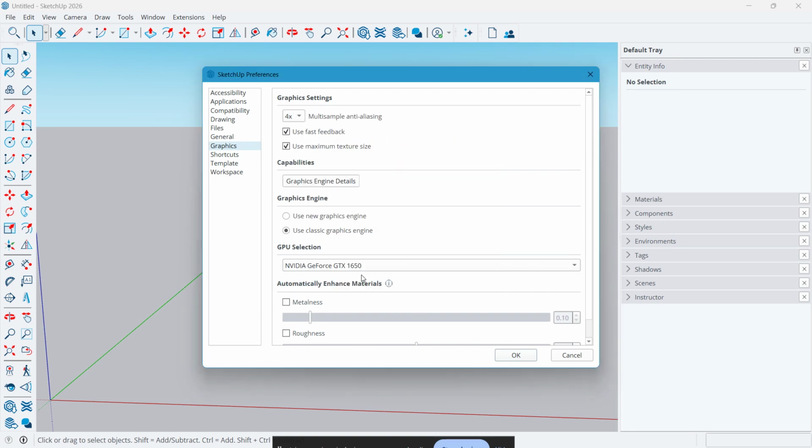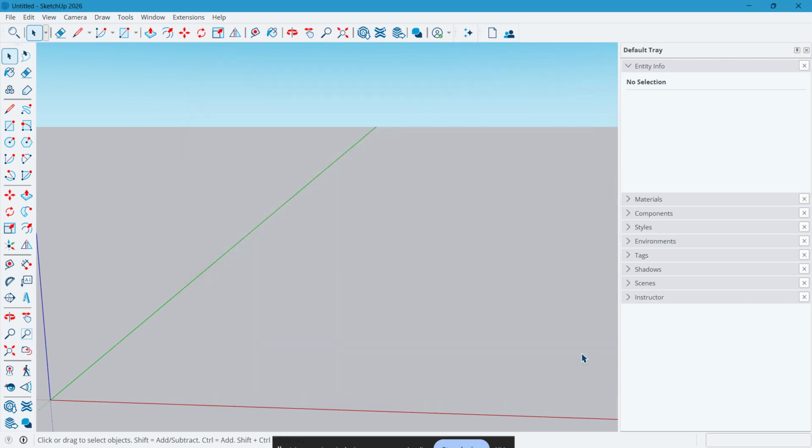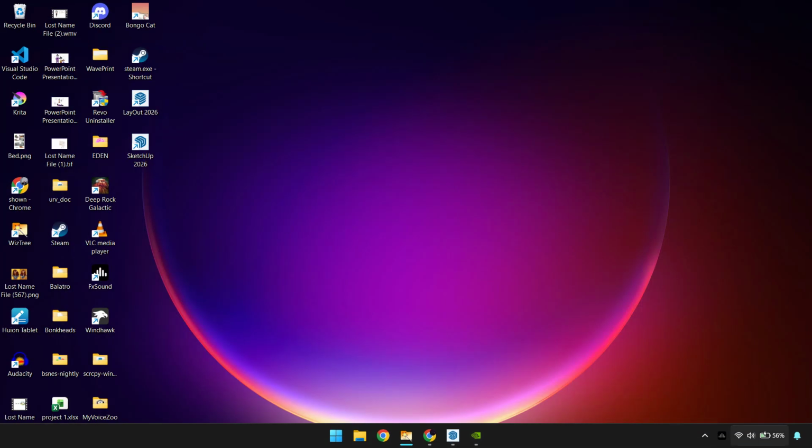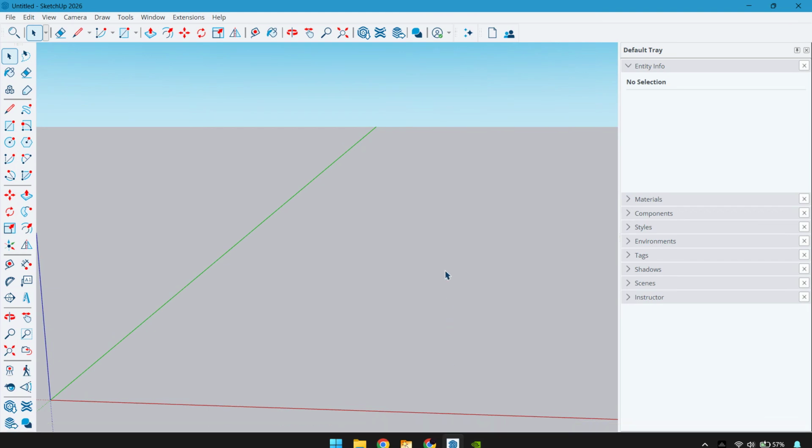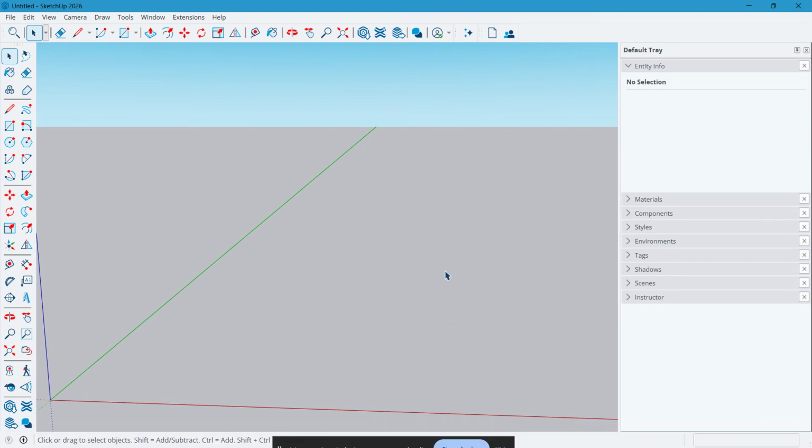If SketchUp was crashing before you could even get into the settings, it will often fall back to the classic engine automatically after a crash, so try launching it again after the restart. This can be a very effective workaround if the new engine is causing the bug splat or the unsupported hardware message. The next thing to check is whether SketchUp is using the correct GPU.